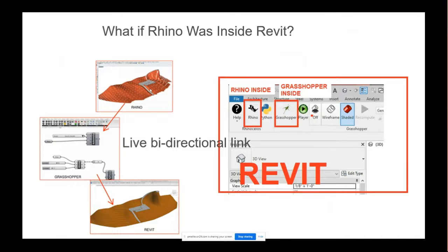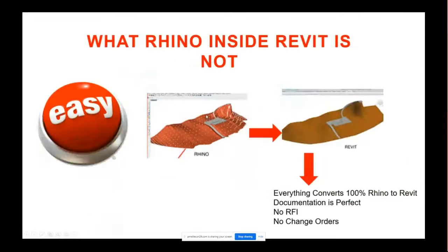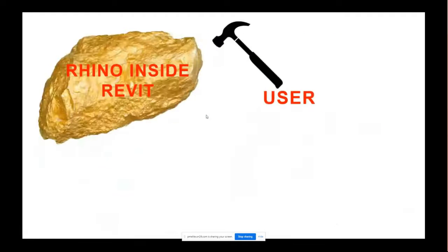Conveyor allows you to take Rhino elements into Revit, although things are preset for you. Rhino Inside Revit is a bit more broad, and you're allowed to be more flexible with how you decide you want information to come over. I'm going to describe the difference in a little more detail here.